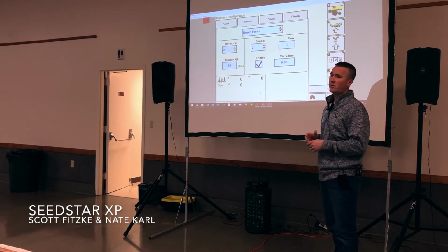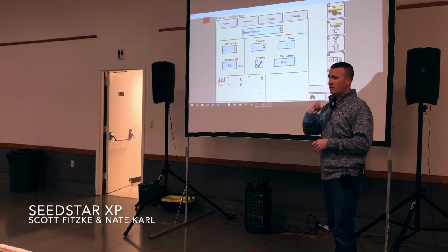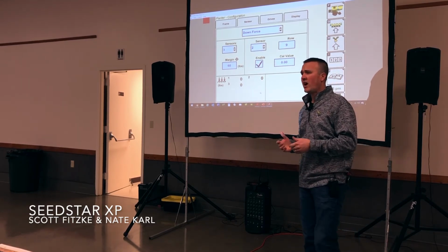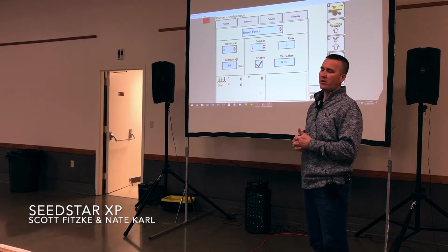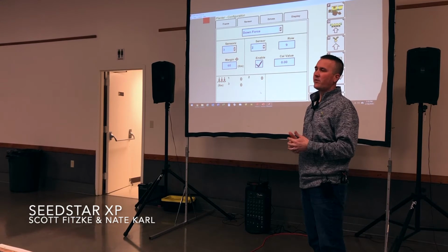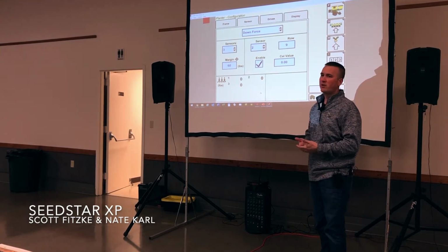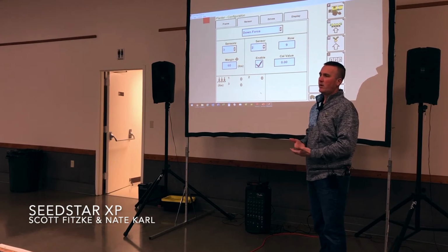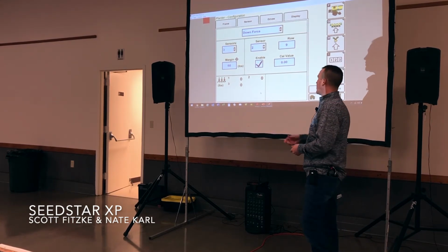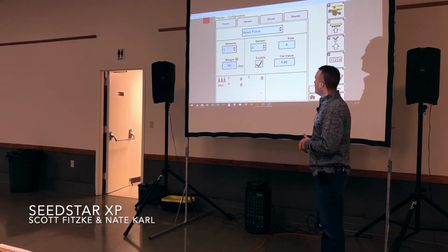it's a good idea to come zero those out because really, we talked earlier about how we're looking at the overall performance of that planter, and if we are receiving bad information in for either ride quality or how hard we're pushing down, ultimately that's going to affect our depth. And that's something we definitely don't want, to come in shallow and have some issues there. So it's an easy way to come in here, re-zero those out, like I said, once a week or so.